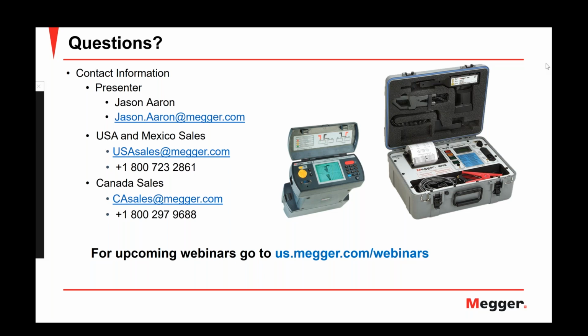Now, the setup to use it with PowerDB is similar. You're going to find the export menu on the receiver and select that. Once you select that, it's going to give you an option to either export that data to the printer or export the data to your computer. To connect the receiver to your computer, there's a cable that's provided. On one end is the connection for the receiver, and the other end is an RS-232 connector that you can connect to the COM port on your computer.